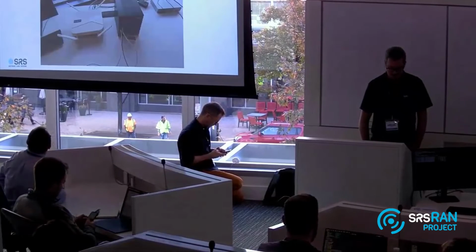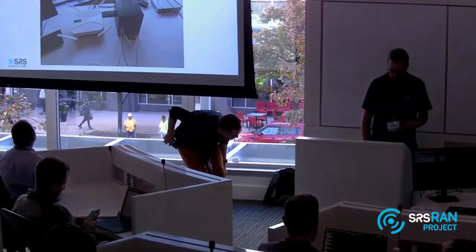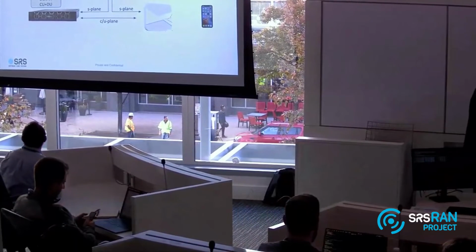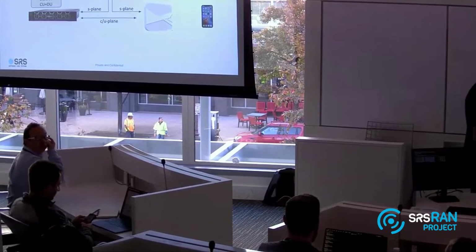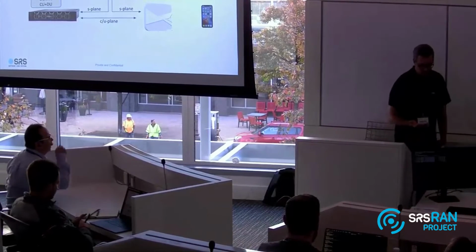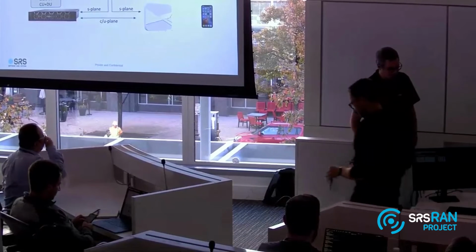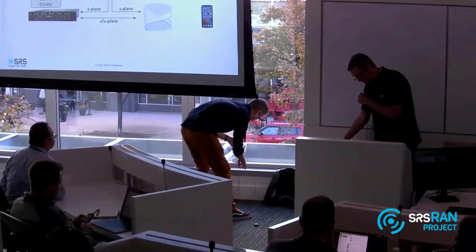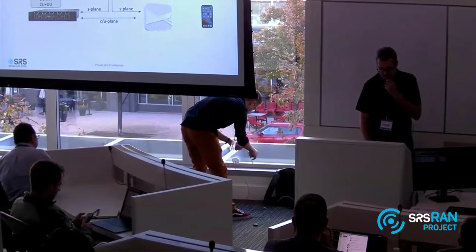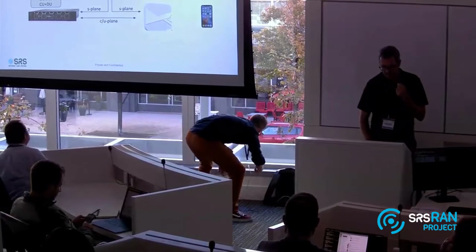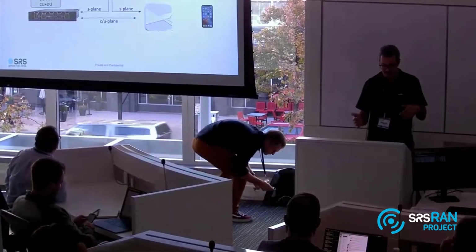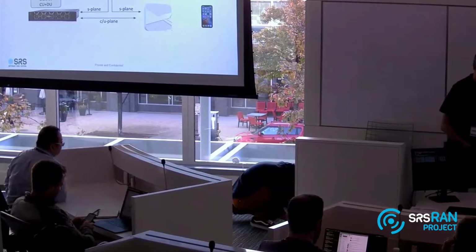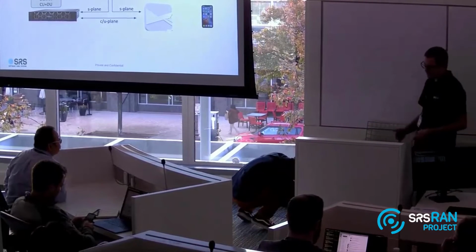This is the setup that I took a picture of yesterday, that we will run today. In this server, we will run the core network and the gNB. Everything collocated in the same machine. And here we have the Foxconn RU. We have here on the ground the PTP Grandmaster from Pulsar. And as you know, in O-RAN, the sync plane is separated from the control and user plane. So this guy is connected to both this and this to drive the timing.